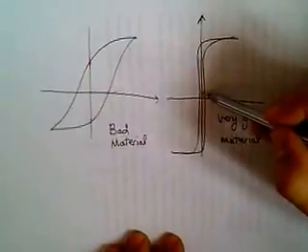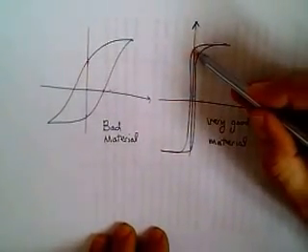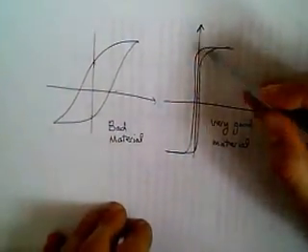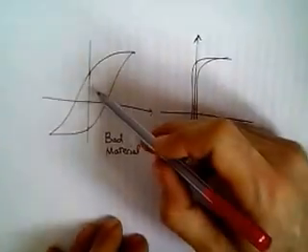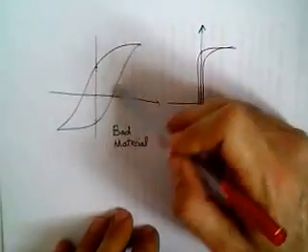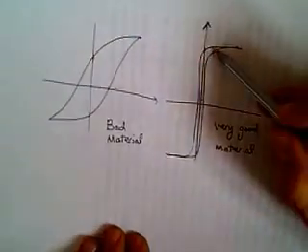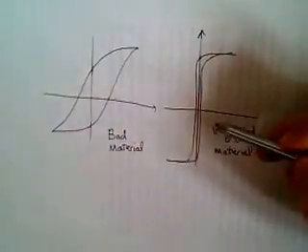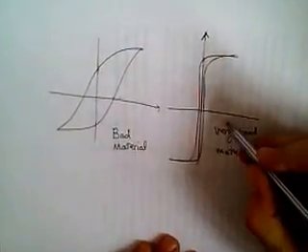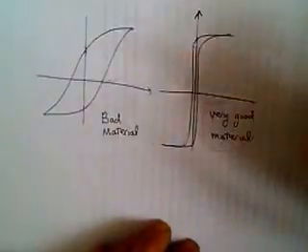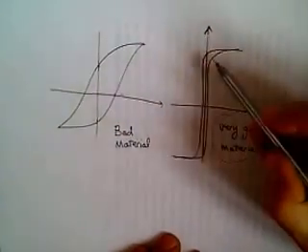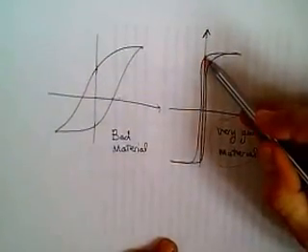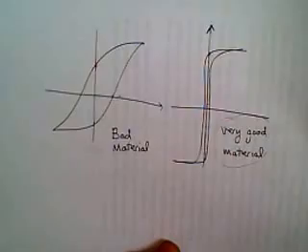But for this material, you can apply current and the residual magnetic field is relatively high, so you can create good permanent magnets with this material. The area under the hysteresis curve is large for this material and relatively low for this material. So this ferromagnetic material is, in those senses, very good for us. Low hysteresis loss, high residual B field, so it becomes a good permanent magnet.